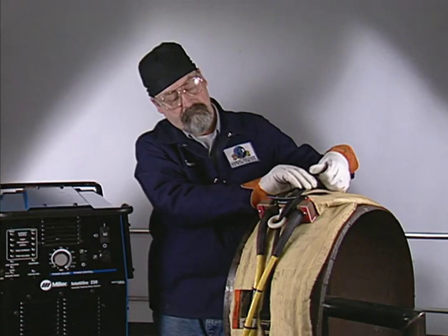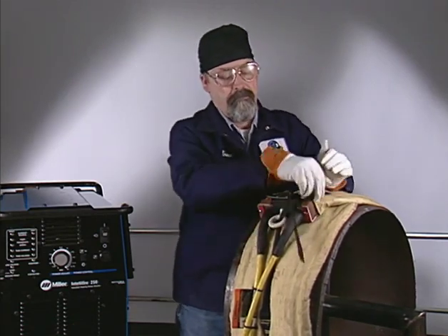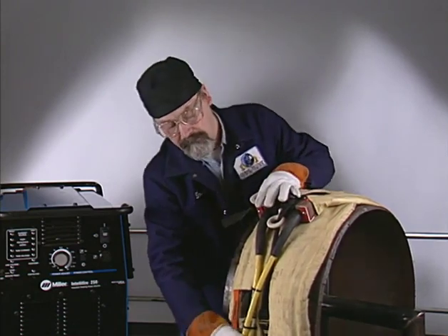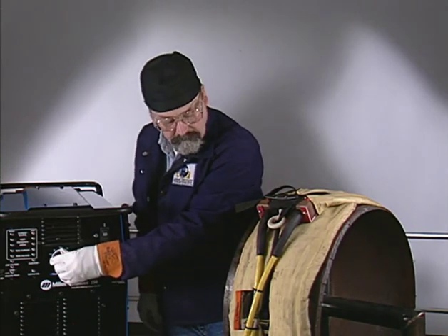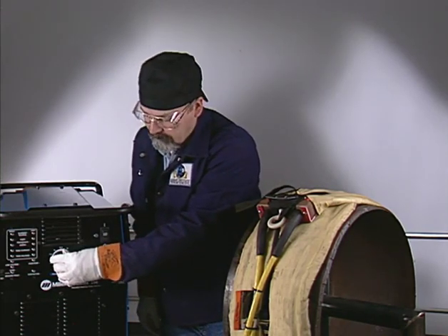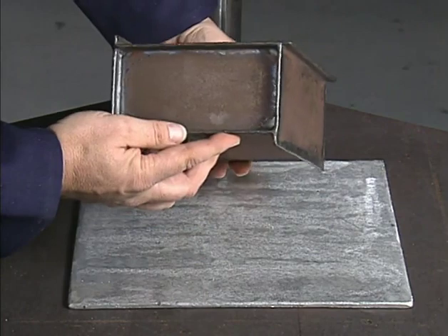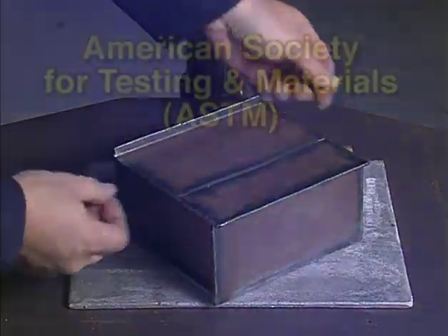Induction blankets are often used for stress relieving, which involves raising the temperature of the weldment between 900 and 1250 degrees Fahrenheit, or 480 and 680 degrees Celsius, and holding the temperature, usually for about an hour per inch of thickness, and then allowing it to cool. You also have to take the history of the metal into consideration because prior welding and heat treatment can change the grain structure and mechanical properties of the metal.